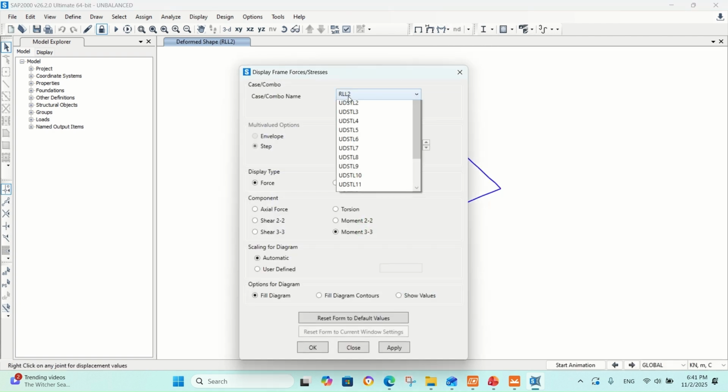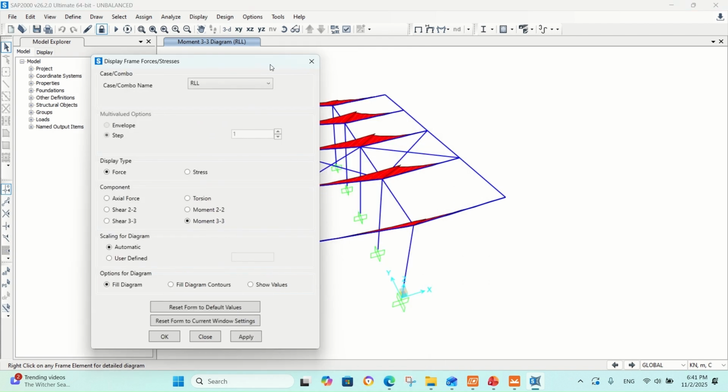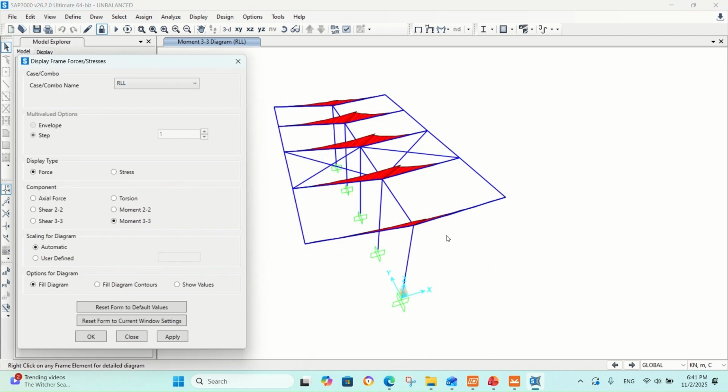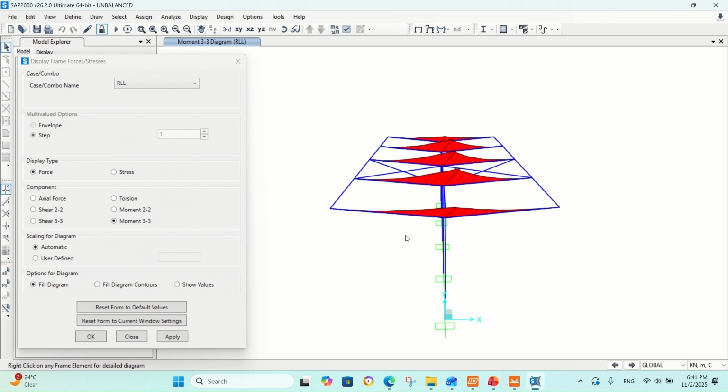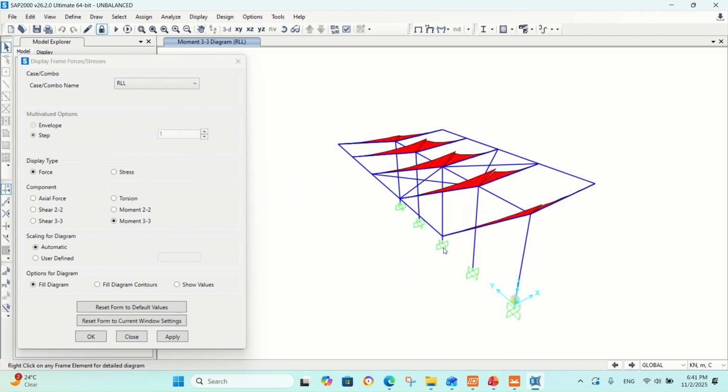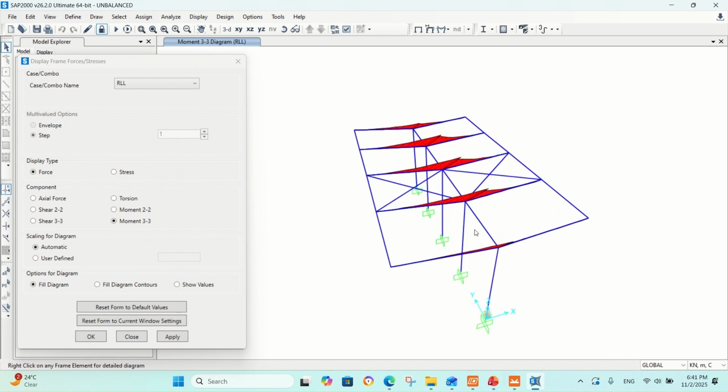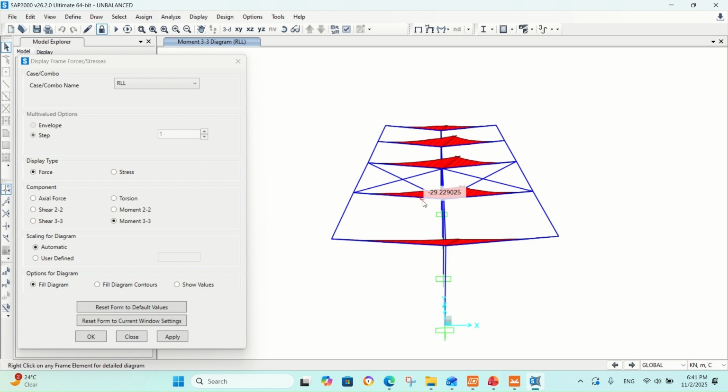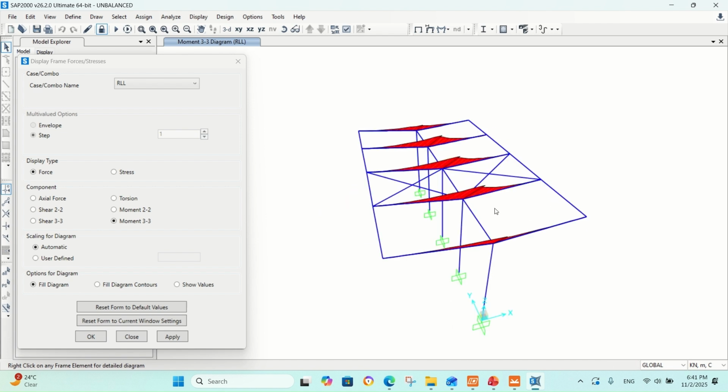we will see that under the roof live load, for example, the balanced roof live load, that we have zero moment at the column due to equilibrium. Because these beams are identical, mirrored, the moment from the left beam will be countered by the moment of the right beam.